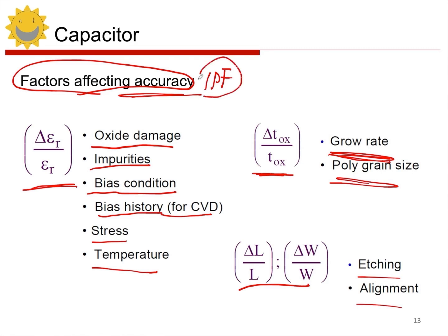But fortunately, in our circuits, the integrated circuit processes can maintain a relatively good level of relative accuracy. The so-called relative accuracy means that for two identical capacitors, the degree to which the capacitance values are close can be relatively well guaranteed. However, of course, if you want the capacitance values of the two capacitors to be more consistent, some sacrifices are also needed, like their area might need to be larger.